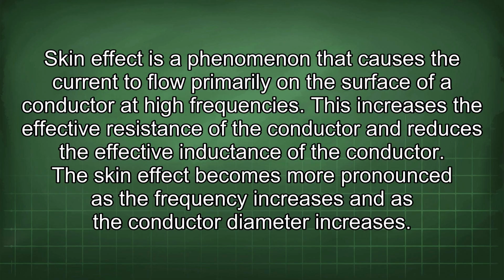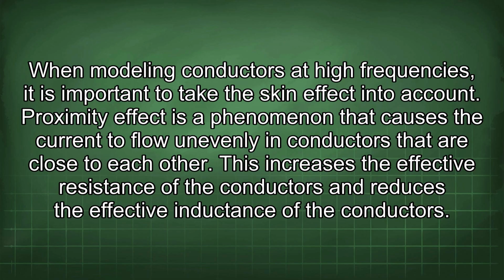Skin effect is a phenomenon that causes the current to flow primarily on the surface of a conductor at high frequencies. This increases the effective resistance of the conductor and reduces the effective inductance of the conductor. The skin effect becomes more pronounced as the frequency increases and as the conductor diameter increases. When modeling conductors at high frequencies, it is important to take the skin effect into account.